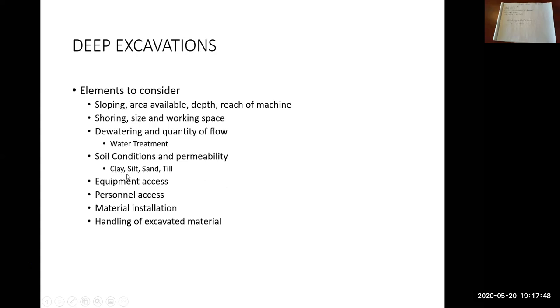So with clays and silts, not very permeable, meaning not a whole lot of groundwater is going to seep through it, versus a sandy type material, water is really going to flow through sand. If you think of being at the beach and you dig a hole right on the shore, you don't have to go down very far to find the ocean water. It's usually right there, and water flows into the hole typically fairly quickly.